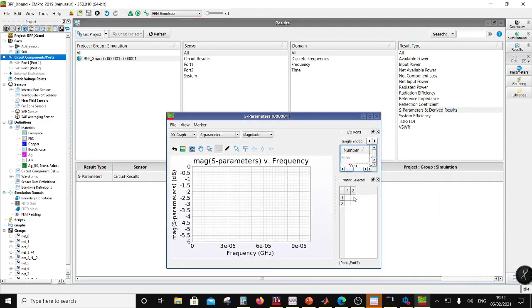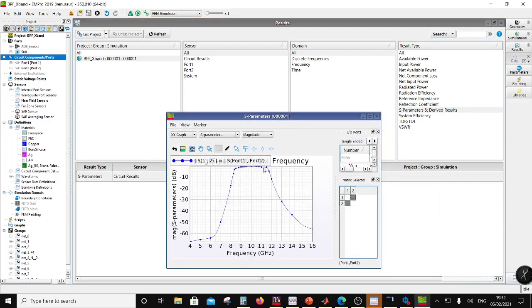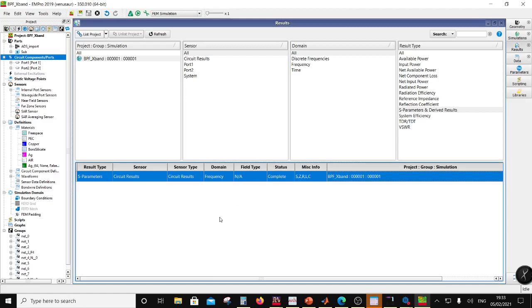So that's going to trim this 9 and 11 excess bandwidth here, right? If you have to adjust that, the 11 gigahertz side will come down by changing that overlap, and then this portion over here, left side, will go up if you slightly change the gap. This is not very accurate, but for practical purposes it's a good starting point. Now I have to put you on pause and look at field data.